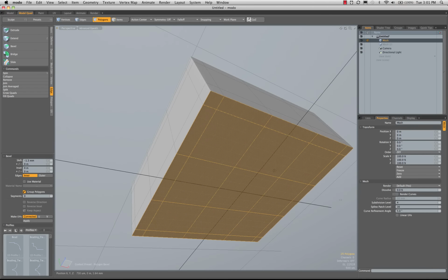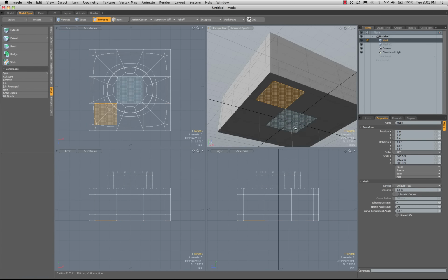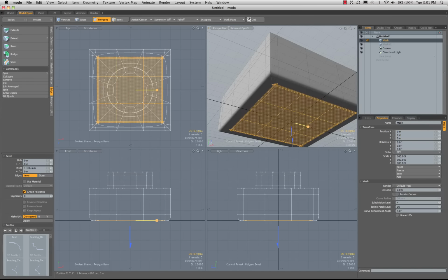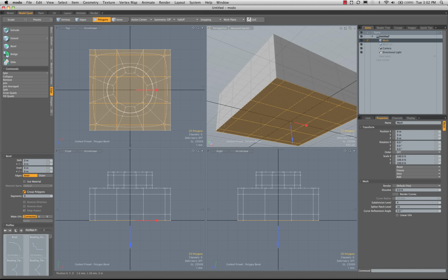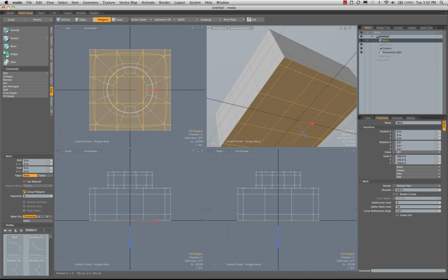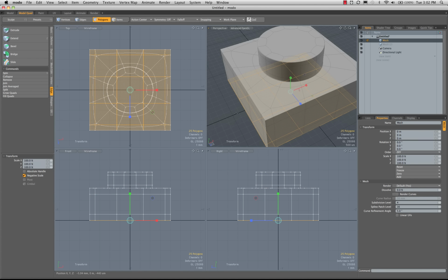The only problem is I'm going to bevel these, and then I'm going to move straight to the scale tool, because if I bevel these, let's select them again. If I bevel these and now just use this, we're going to get overlapping and crossing well before we ever get where we need to go with this. So obviously beveling and using that inset, not going to work. But if we bevel and use the scale tool, which is what we're going to do, we're left with the problem of not being able to tell exactly how far this needs to go in. I mean, granted, you could do the math, but this is going to become problematic.